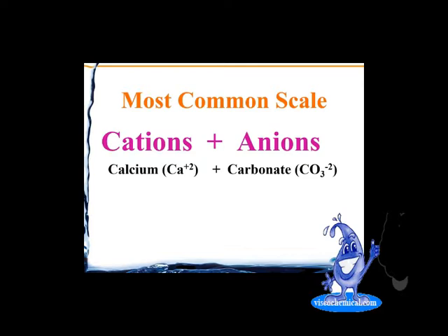If we concentrate them more than that, then we're going to scale unless we have done something in pretreatment to keep us from scaling. So again, softening or acid injection or scale inhibitor injection.